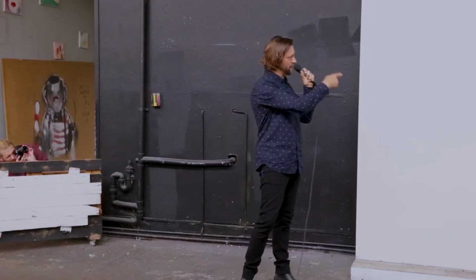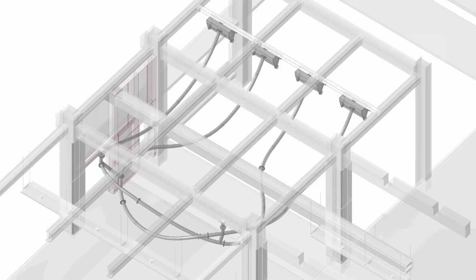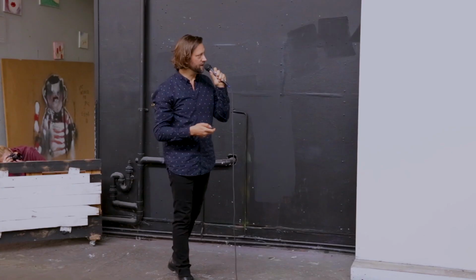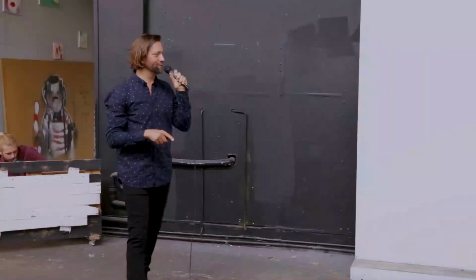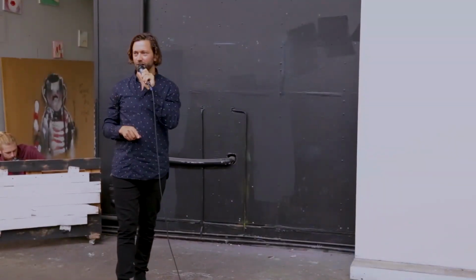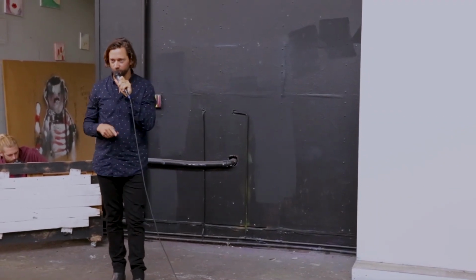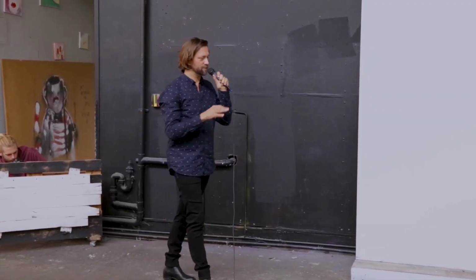We came up with this central spine, a tube that was connected between these different points of the building. That seemed pretty straightforward. It would be the main structural load for the cantilever between the different points. And then we would attach the treads to that central pipe. That all seemed pretty straightforward and awesome. And then Transport came back and said, "No, you've only got 48 hours to install it." And so from 2.5 weeks, which was in the contract, they said, "No, you've only got 48 hours to build this." So we had to completely change the design.